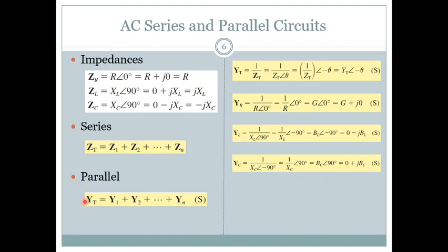So total admittance is the addition of admittances. Admittance is the reciprocal of impedance, so Y is equal to 1 over Z. That is what is shown here. Once you find the reciprocal of each component, or the admittances of each component, you can add them together, rather than using the parallel impedance equations, because now this is complex, we have to work with phasors and complex numbers.